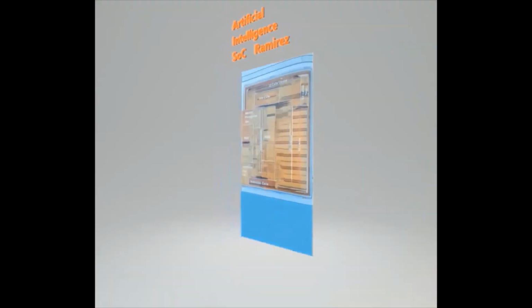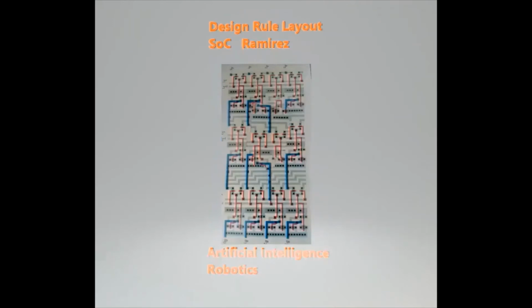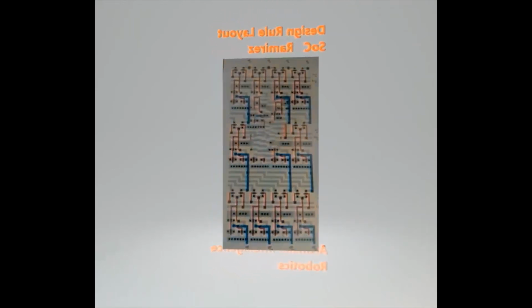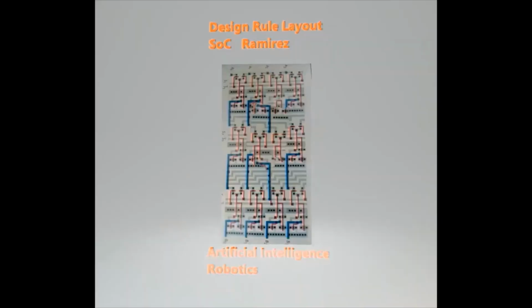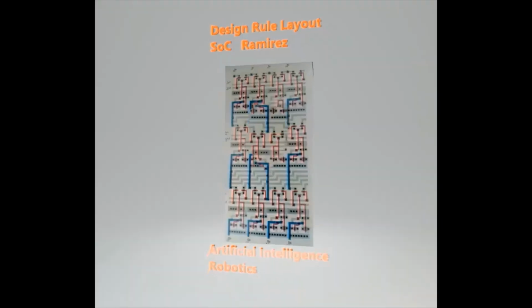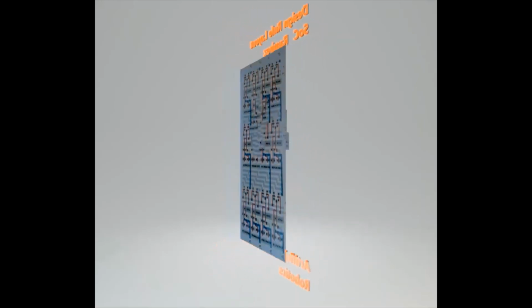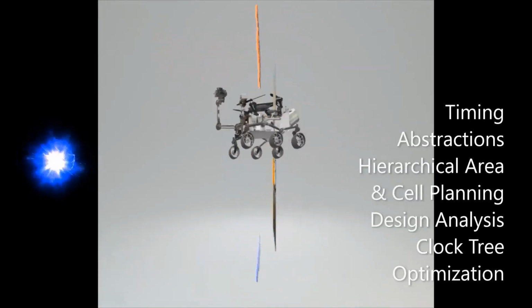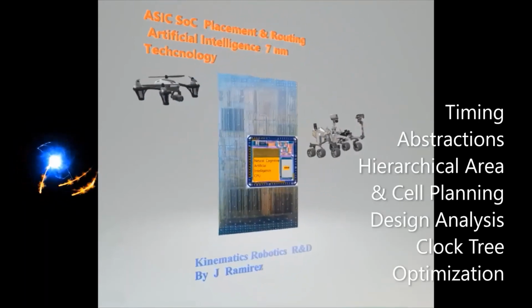The fundamental unit in the definition of a set of design rules is the minimum line width. It stands for the minimum mask dimension that can be safely transferred to the semiconductor material. In general, the minimum line width is set by the resolution of the patterning process, which is most commonly based on optical lithography, or E-beam lithography in this case.